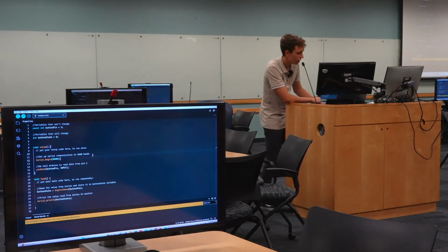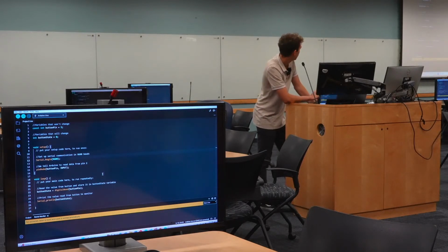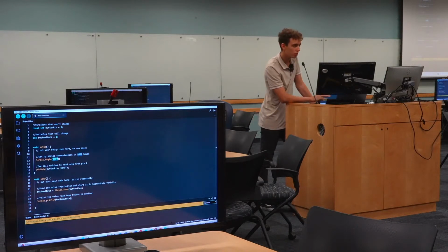And then another thing you need to set up if you're using serial communication is the Serial.begin. Again, this part is very important if you're going to be debugging with the serial monitor. You're saying Serial.begin, and here is the number, which is a parameter. That's called the baud rate, and you're telling the Arduino at what frequency you want to listen to the physical port, which is our serial monitor in this case, or serial communication.